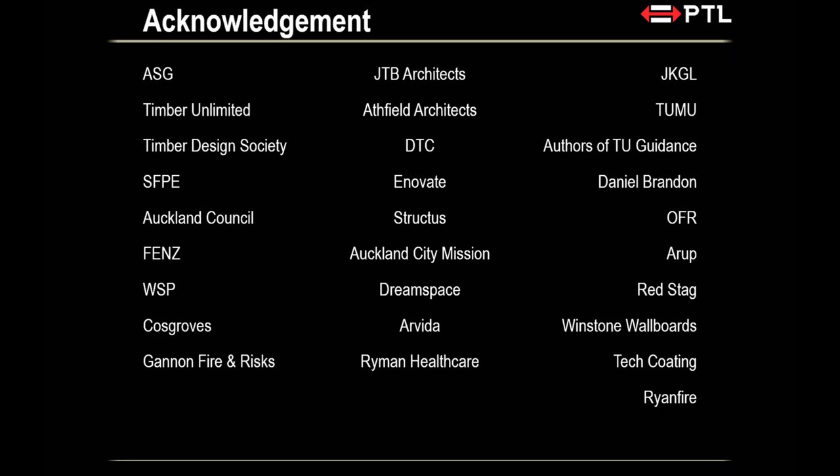And I'm not saying that for all your risk, because if you're just doing a 2-3 story walk-up, come on, you need to get out of your home when it's on fire. But if you're doing a 20-30 story high-rise mass timber with interconnected floors, you can't solve the mass timber problem by just applying a passive or fire resistant rating to it.